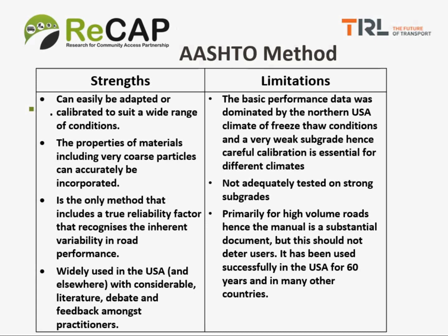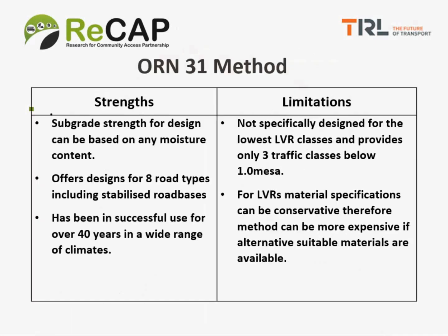Limitations, the one that's probably most serious from our point of view, it is not adequately tested on strong subgrades, but as I say, it can easily be calibrated to do so. It's primarily used for high volume roads, hence the manual is a thick, substantial document, but this should not deter users. As I said, it's been used successfully in the USA for 60 years and in many other countries.